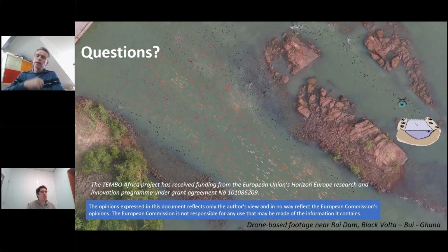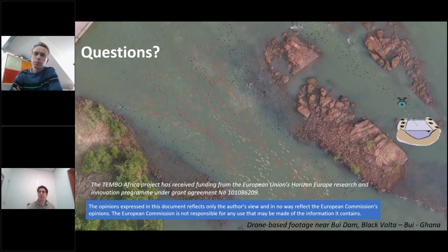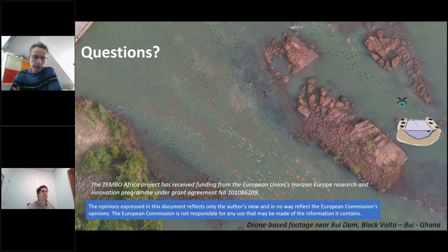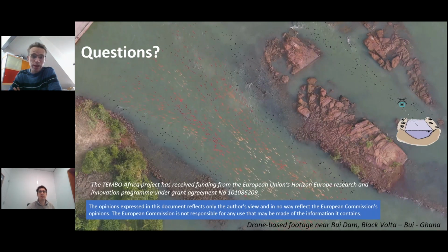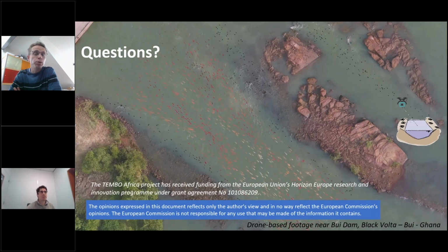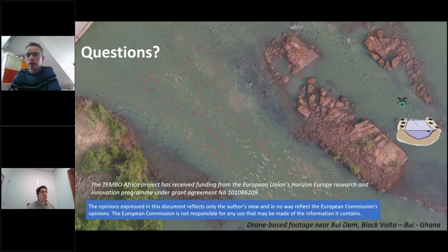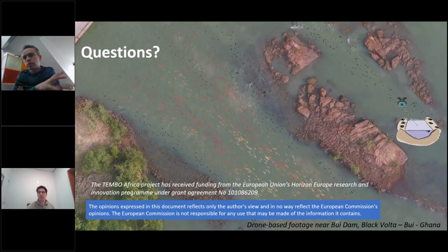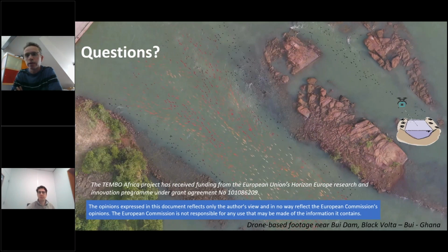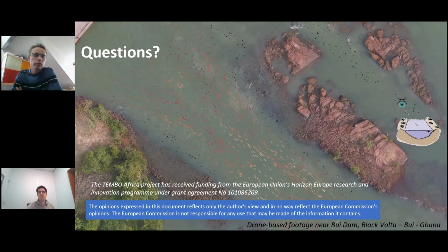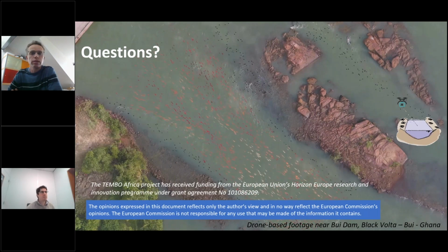Low flows, yes. Well, it's especially low seeding conditions that you have to be worried about. So especially the library PyOpenRiverCam has a lot of methods to pre-process the frames so that you do not get spurious velocities. Of course you can't estimate velocities if you don't have tracers, but if noise becomes higher than the signal, you have to make sure that you get rid of the noise before you actually process the video. So that is key, that you pre-process so that you simply do not get a velocity under those conditions.